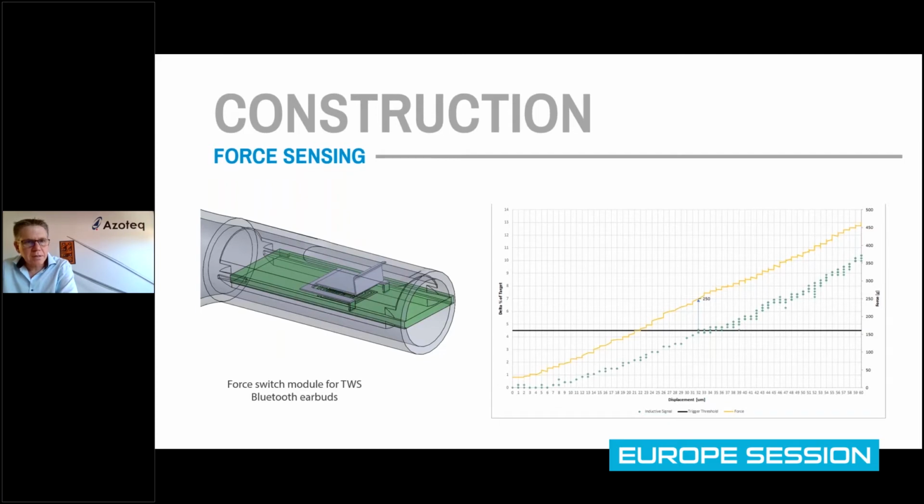And the other big advantage, gloves. If you are using gloves either because you are cycling or you are in cold temperatures, then force sensing is a nice user interface, whereas with gloves and capacitive sensing, it is always tricky to get that right. If you tune it too sensitive, then it works with thick gloves, but you can get false activations. If you don't tune it sensitive enough, then the thick gloves are not working.